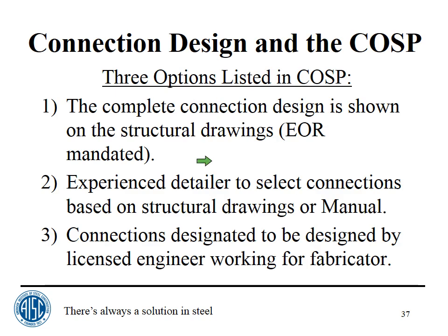The only thing that I'm talking about here for the Code of Standard Practice is there are three options now for connection design. Option one is that the complete connection design is shown on the structural drawings. These we refer to as EOR, or Engineer of Record mandated. Option two is experienced detailer to select connections based on structural drawings or manual.